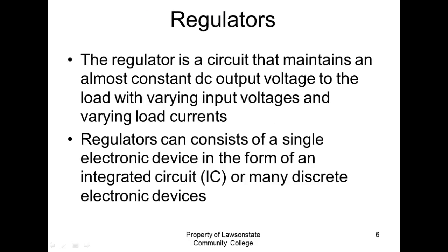So the regulator is the circuit that maintains an almost constant DC output voltage to the load with varying input voltages and varying load currents. Regulators can consist of a single electronic device in the form of an integrated circuit or many discrete electronic devices. So we'll look at both of these. You can buy variable voltage regulators and fixed voltage regulators. We'll take one of the trainers apart and look at the power supplies in the trainer.